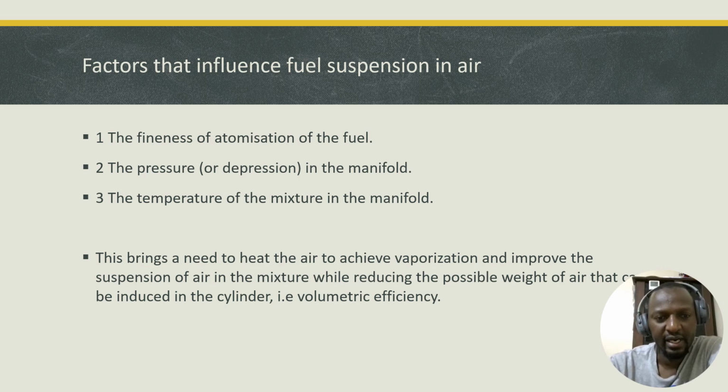And thirdly is the temperature of the mixture in the manifold. Remember, we said that we atomize the fuel first and then it absorbs the heat from the manifold to vaporize. This brings the need to heat the air to achieve vaporization and improve the suspension of the fuel in the mixture, while reducing the possible weight that can be induced in the cylinder. That is the volumetric efficiency.